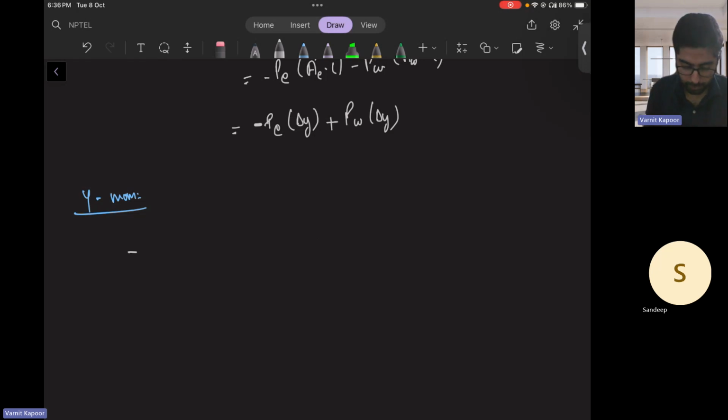So your equation was J dot del P dV over the control volume is equal to minus J hat summation over all the faces PF AF.